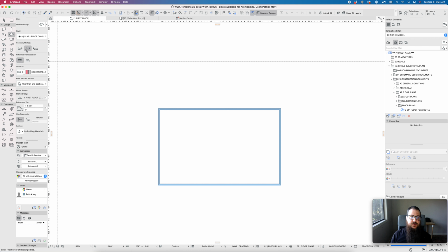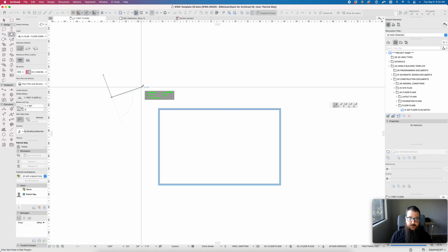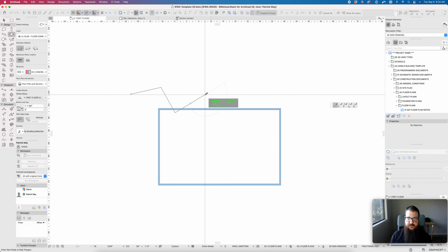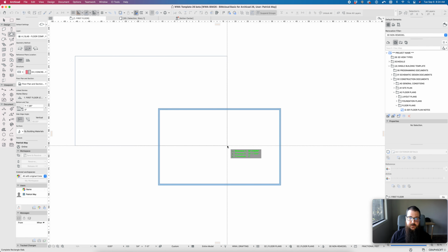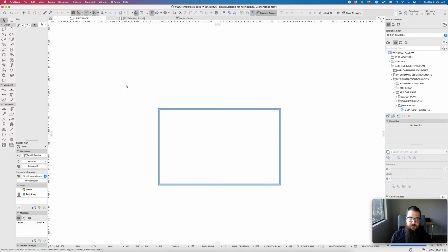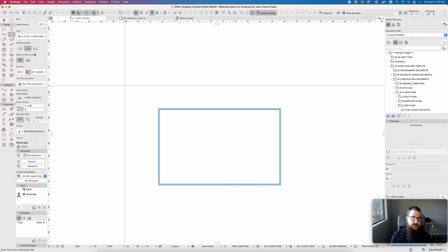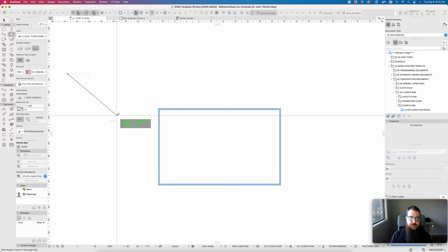piece right here. So with geometry method, you really only have three options with the slab. It's either polygon, just like with the wall, and again, the delete key versus the escape key. Delete key is going to cancel the last placed node, and escape is going to cancel the whole placement. You can place a rectangular slab, or go back here, you can place a rotated rectangle.